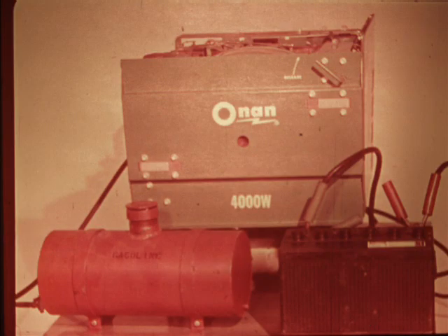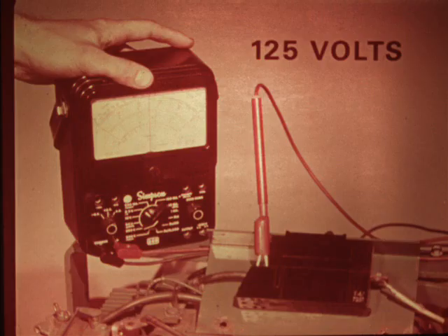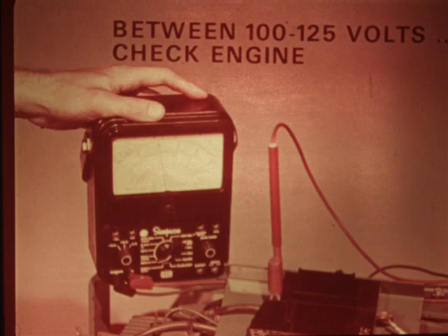Then, be sure to test run the generator before you put it back in the vehicle. Put the fuel inlet into a gas can, connect a 12-volt battery, and start it up. Use a voltmeter or test light to check for output at the main circuit breaker. If the generator is okay and the engine is at the right speed, the meter will read about 125 volts. However, anything over 100 volts but less than 125 usually indicates that the generator is good, but the engine driving it needs service. We'll get to low-output engine problems in a minute.